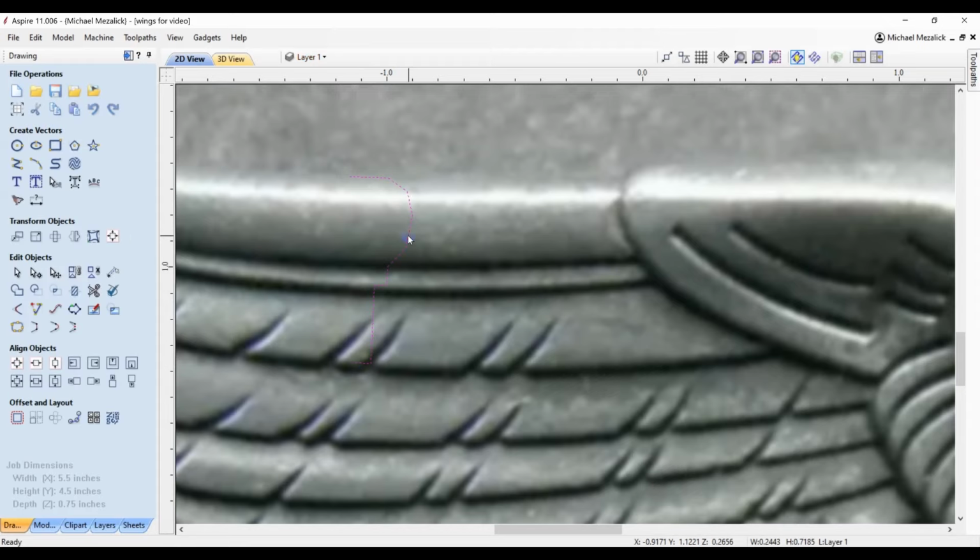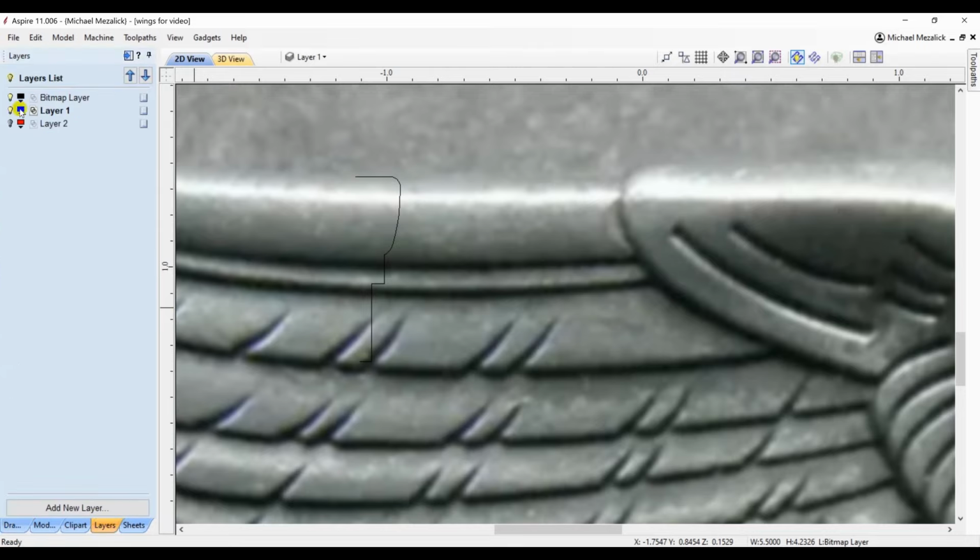Clicking on that shape and hitting the N key to enter into the node edit mode, I can adjust the nodes as needed. My first step usually is to change them to Bezier curves by hitting the S key where needed, and of course moving them to fit the profile as I think it would be. So drawing vectors and node editing becomes an important part in any 3D modeling process. I changed the color so I can see it a little bit clearer.